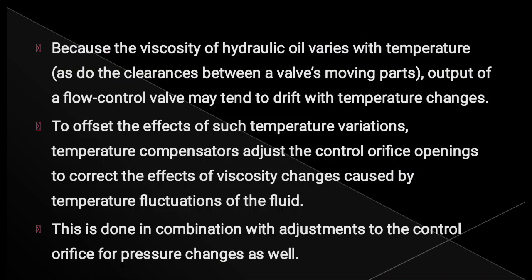The viscosity of hydraulic oil varies with the temperature, as do the clearances between the valve's moving parts, so the flow control valve may tend to drift with temperature changes. As you know, as the temperature increases in a system, the viscosity of a liquid reduces. That may lead to improper pressure, and the pressure is not going to be adequate. So the reduced viscosity considerably reduces the pressure, and the operation of the actuator is going to be affected.